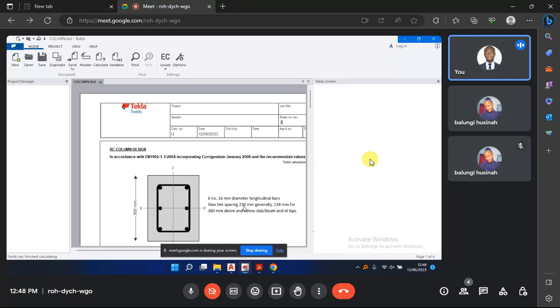That below at the column there is a lot of shear, and when you check the diagram of shear, you realize that the maximum shear is at the start and at the top. So some people, when they want to economize, will have smaller link spacing towards the column, and at the end, then in the middle, they will have a bigger spacing, say 200.